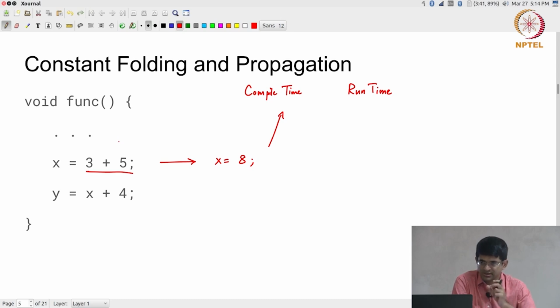One of them is a preamble size, some number of symbols to be sent out as pilots, the number of symbols that are incorporated in one packet of data, and the number of packets themselves. Now you are not going to be changing those at runtime, but you do want the flexibility of being able to change them at least at compilation time to target a different piece of hardware, which means the compiler can then reduce all of that to a single number and use it from there onwards. This simple, fairly obvious thing is called constant folding.